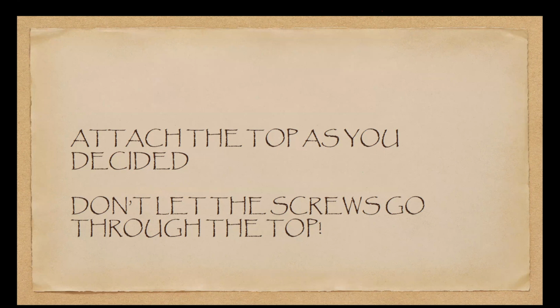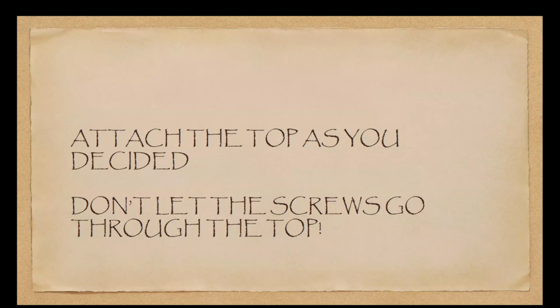What I have done tonight is to try to describe a summary of the idea, draw plans and work on a cut list, plan the sequence of cuts, any additions such as stringing, banding, embellishment, escutcheons, veneer inlays. Think again about the sequence of cuts and how you want to manage those. And I've discussed some finish options. One more reminder, measure twice, cut once.